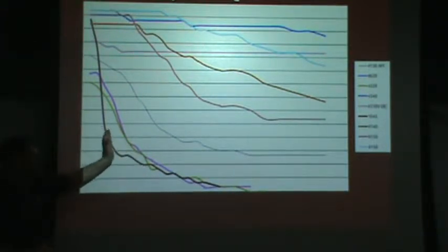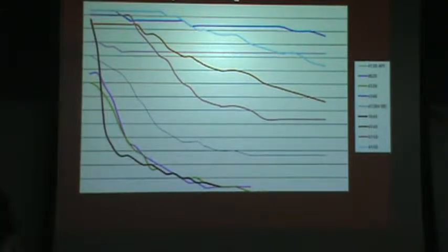And so you're not seeing 10 different grades on one chart, it's just one, but they do show you two curves. Every chart in there has two curves on it, a higher curve and a lower curve. And the reason for that is because when you order steel from a steel mill, you say to the steel mill, I want a specific chemistry range. You don't give them a specific number for each element because it's very difficult for a steel maker to hold to a specific number on every single element. So you always give them a range. Now sometimes the range might be pretty narrow, sometimes it might be wider, but you always give them a range.